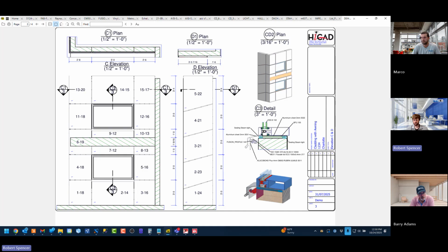As well as, Marco, I think I asked you this before. Do you have certain layers that you need created for your exports for the cam? Do you have an example of that? No, we typically just go for a pretty flat 2D drawing, just XY coordinates only, and then the layers are added with the tool pass that determines the Z. So my drawings, single layer is better for me because this Alphacam gets a little funky when you start getting too many layers and work planes in there.